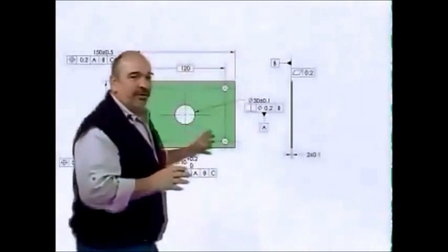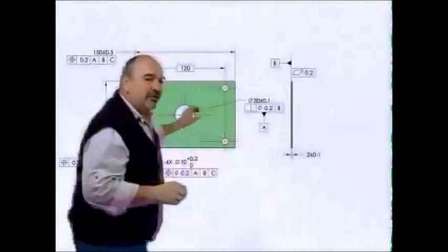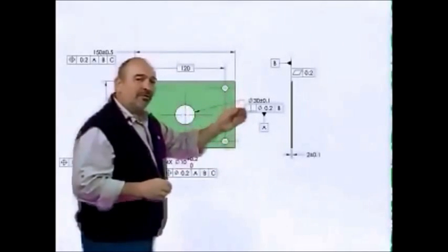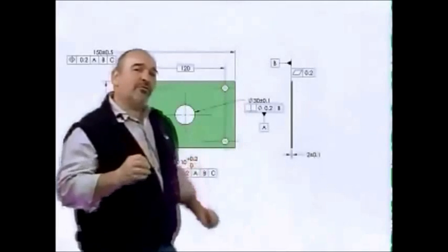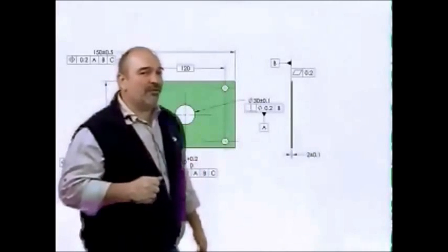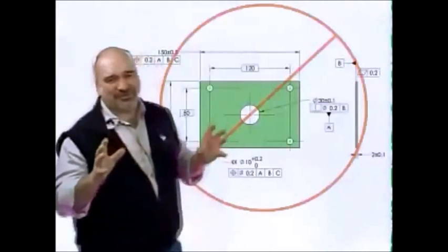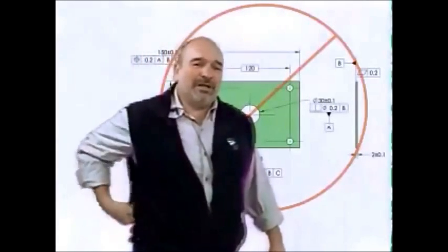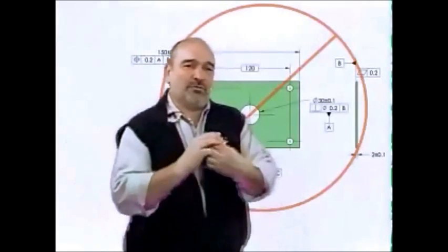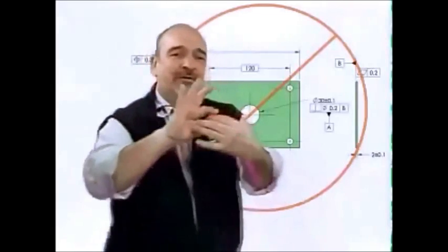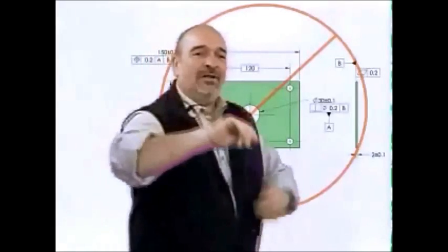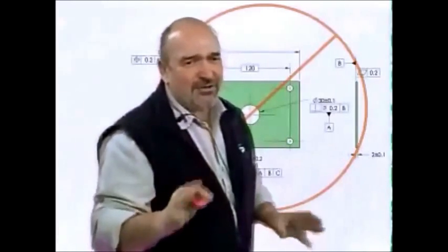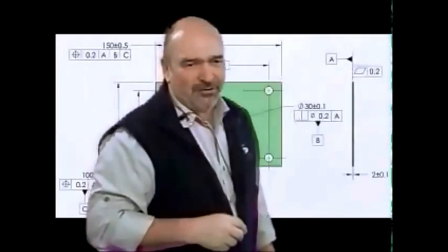On this drawing, the primary datum feature is this large hole in the middle. Now this is a thin part. We're asking this cylindrical feature that's not very long to take away 4 degrees of freedom. That's ridiculous. This hole isn't long enough. That would be like trying to reproducibly grab this disc by the diameter. You just can't do it. If you do this on a drawing, please do not tell anyone that you've been reading my tips.